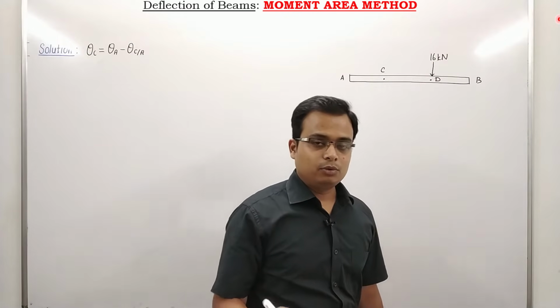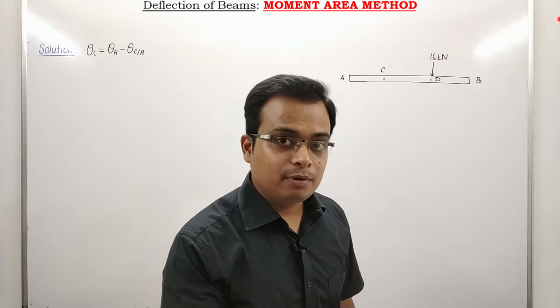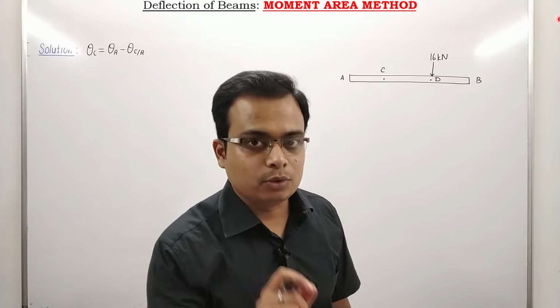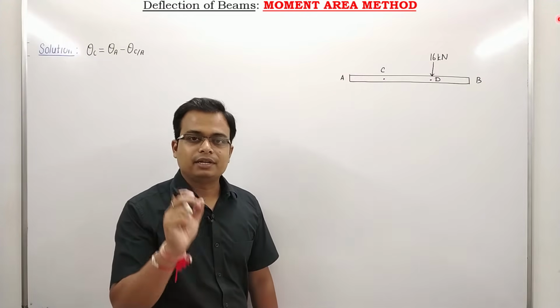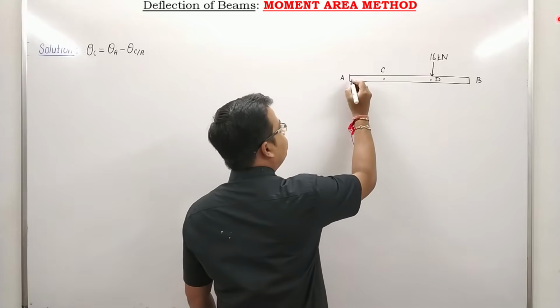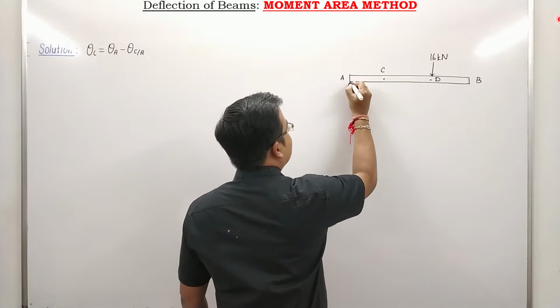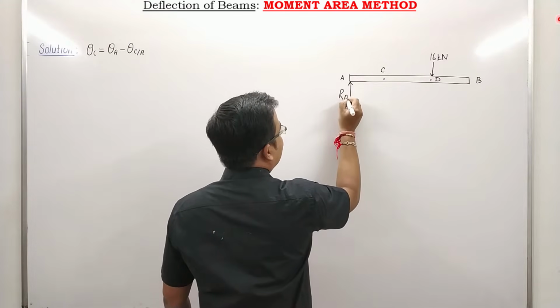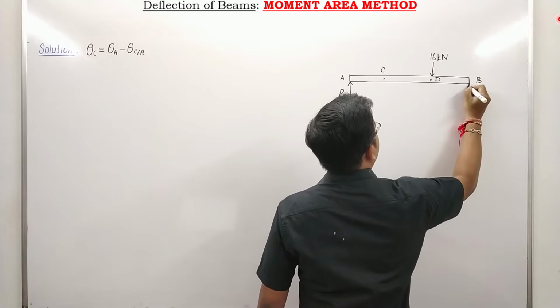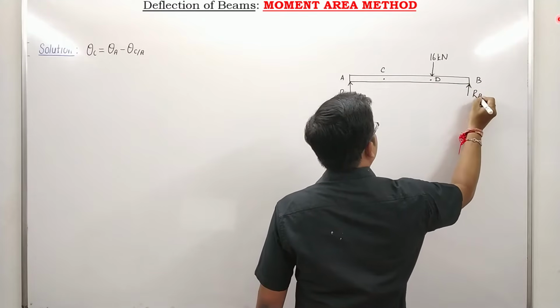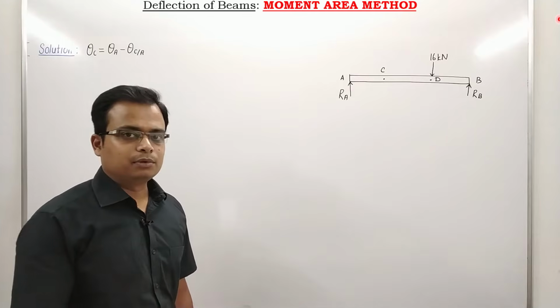But before that, you need to know the bending moment values, and even before knowing the bending moment values, what you need to know is the reaction at supports. So we've removed the supports. They can be replaced with these reactions, that is RA for you, and this over here is RB for you. Just take a look. This is very simple.